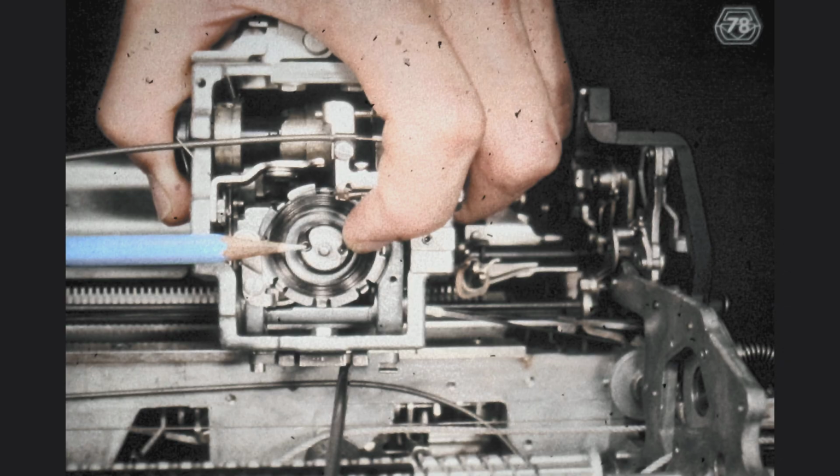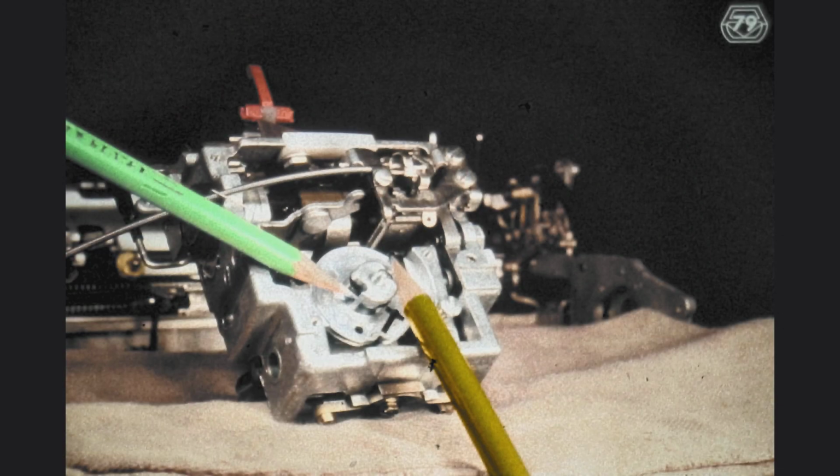Notice that when viewed from below, the spring is constantly trying to rotate the rotate pulley, or shaft, counterclockwise, keeping the rotate tape taut. Don't let this confuse you. When viewed from above the typewriter, this becomes clockwise rotation. The rotation of the rotate spring means that the rotate spring tries to rotate the element in a clockwise direction when observed from above the typewriter.